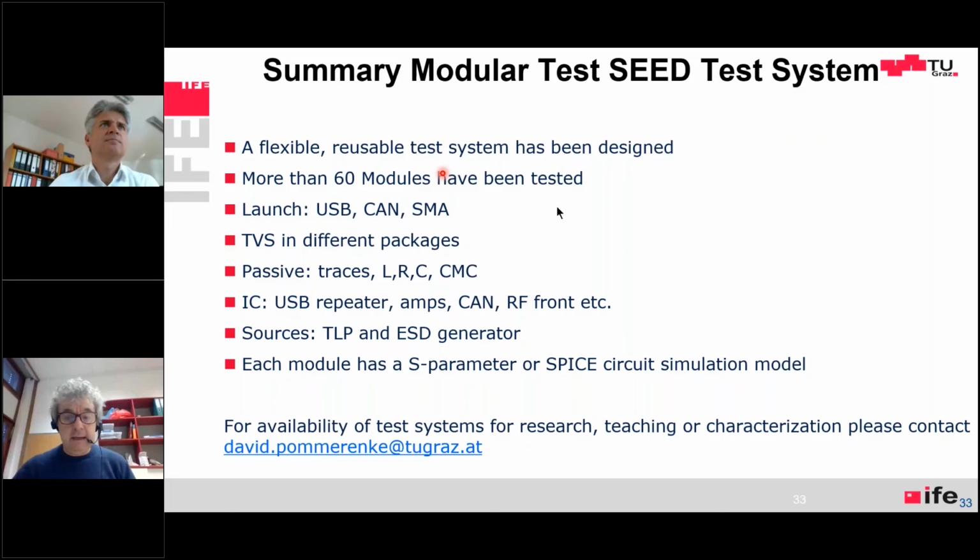So, what I wanted to say, a TLP is the most simple thing in the world. Think about, you have a coax cable here, and the inner conductor, and this coax cable you charge up, inner to shield, and there's another coax cable which connects to your 50 ohm system, and you connect them with a relay, and this relay switches in picoseconds, 50 picoseconds or something.